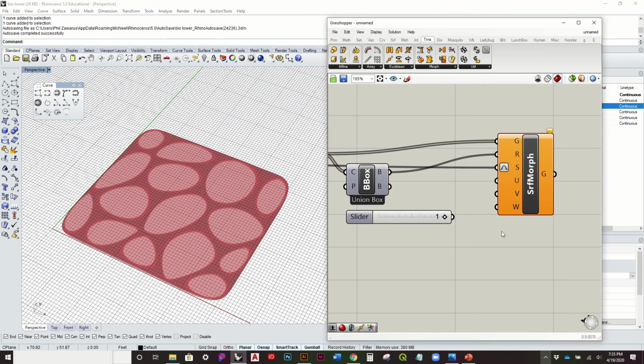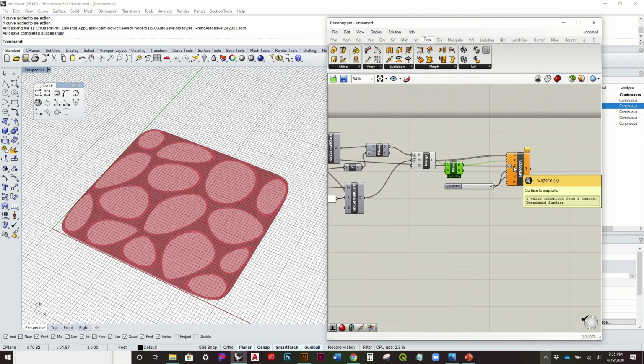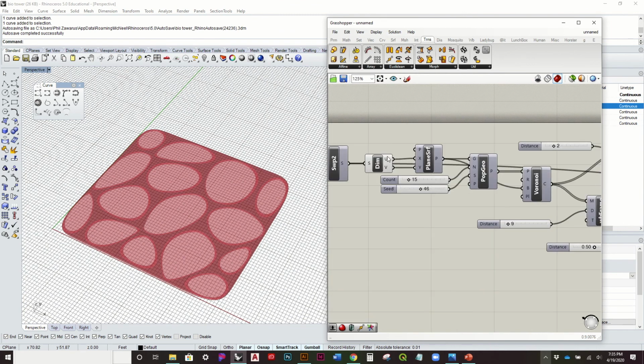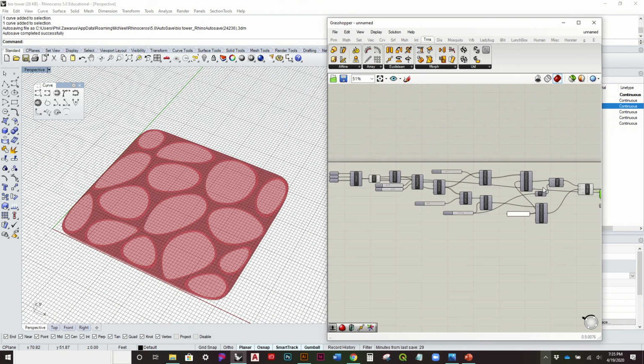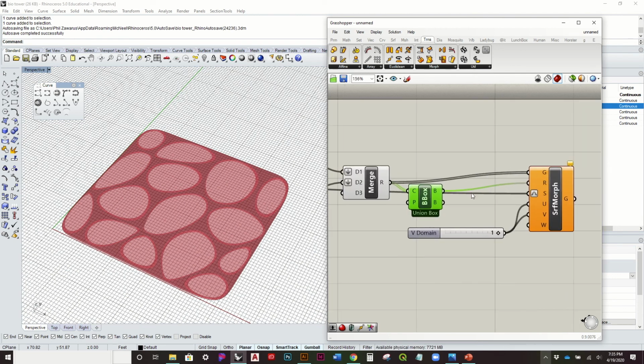And in order to get that to work, I want a number slider of 1 for both our U and V, because we've taken that parameter dimensions, which if we look at it, come out to 61 and 53. And by reparameterizing, it basically just scales that down to be 0 to 1 in both directions. So that's why we use this UV value.